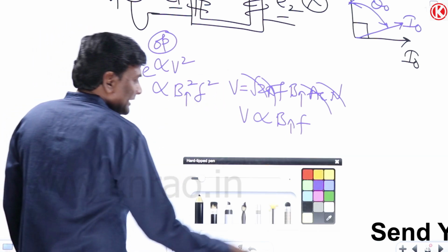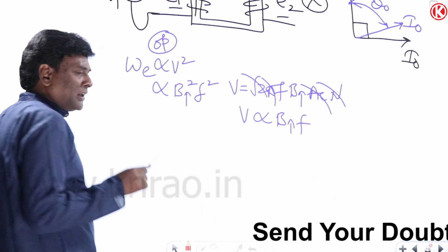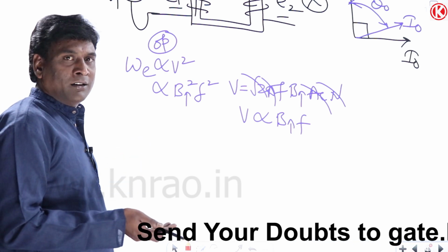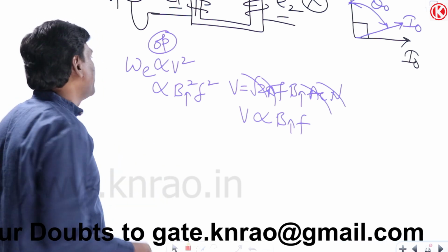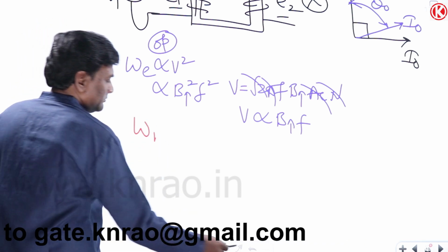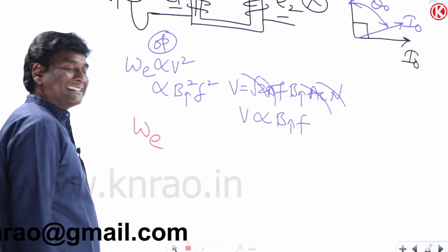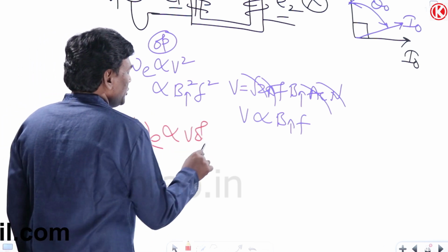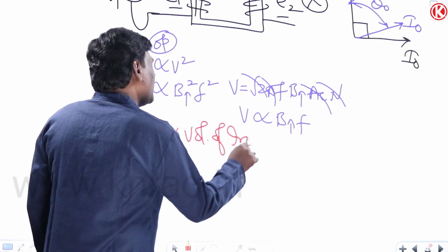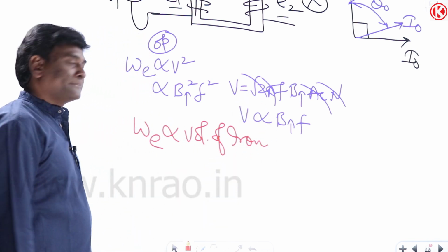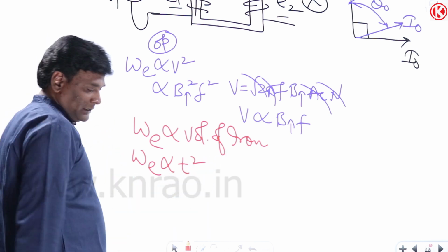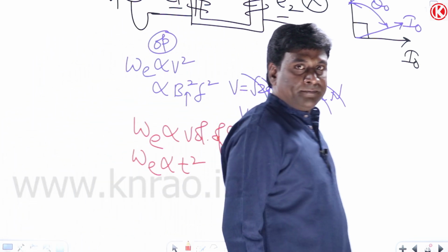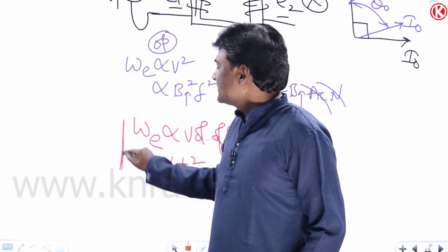Now let us think of it as design engineer. I'm not going into the reasons and all, directly I'm giving how to make the concepts concise, that's it. Now, eddy current loss as designer is directly proportional to the volume of iron, because immediately after this we are going to take a beautiful problem, you would understand. And again, eddy current loss is directly proportional to the thickness of lamination square. These two, as design engineer.